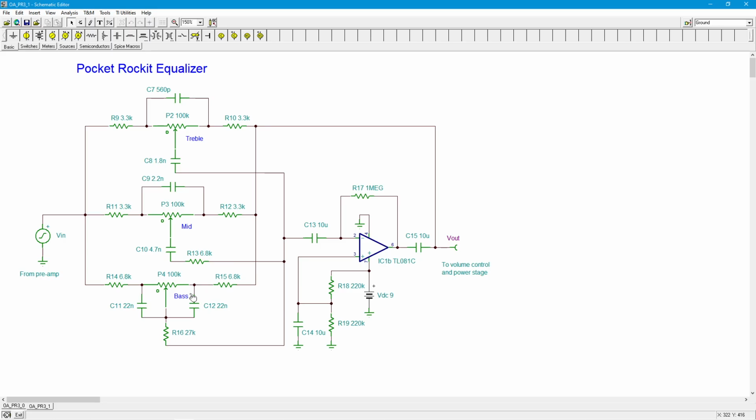Here's the way to look at this. You're essentially looking at an inverting amplifier, right? So across the amplifier, from the output back to the minus input, there would be a resistor, RF. I'm not talking about R17, just ignore that for a sec. And then you would have another resistor, Ri, the R in, coming off to the driving source. It's the ratio of those two resistors in an inverting amplifier, RF over Ri, that creates the gain. So if I had a 10K and a 1K, I'd get an inverting gain of 10.